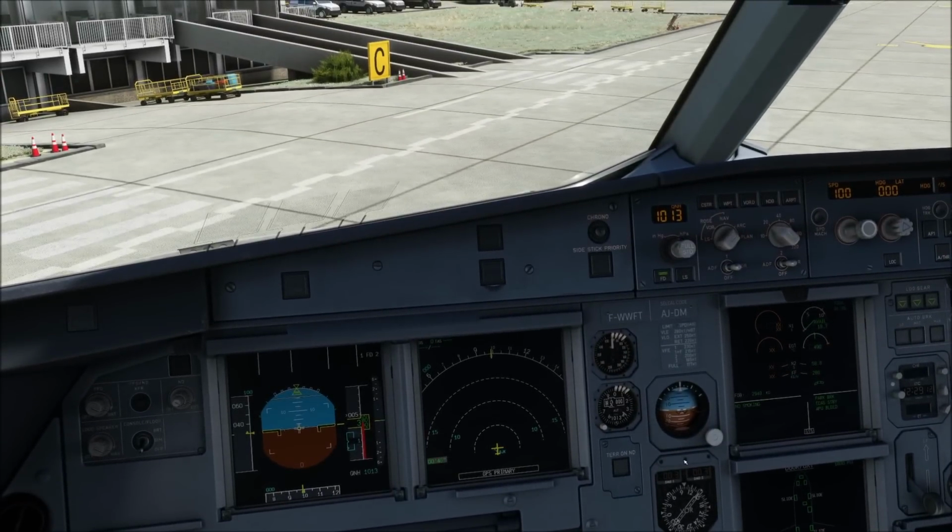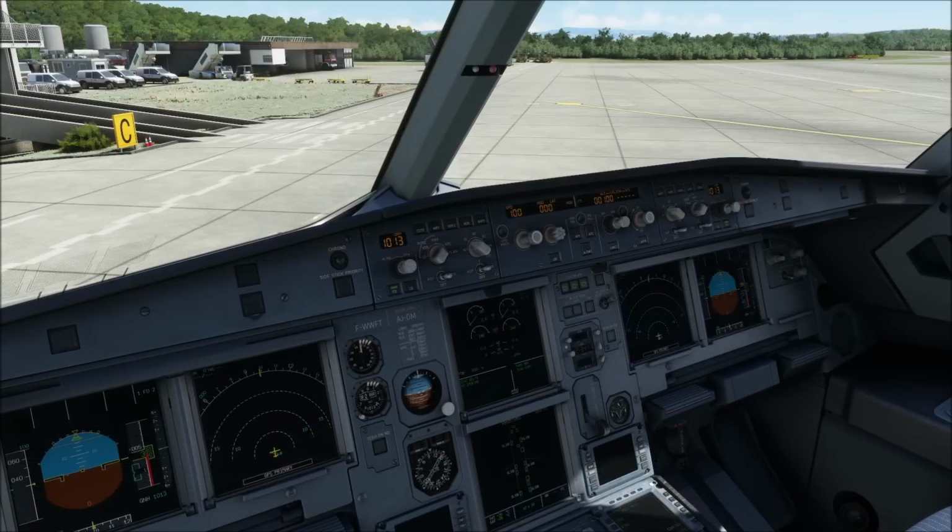Now let's quickly reload, and I'll see you again on the way to start the AIRBUS engine number 2. And up to the next one: engine start with an air start unit. Before we connect the air start unit, we have to make sure the packs are off to prevent any possible contamination of the packs by the air start unit.